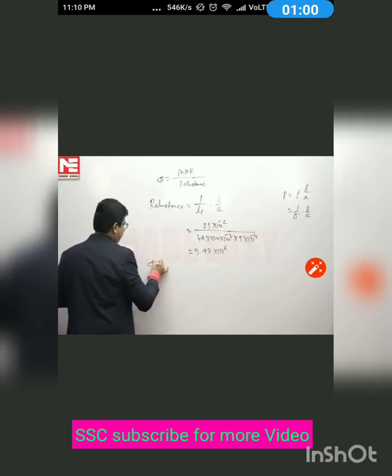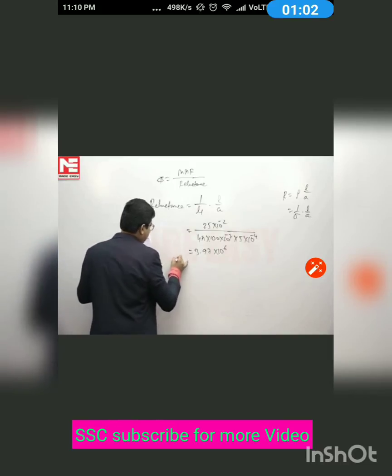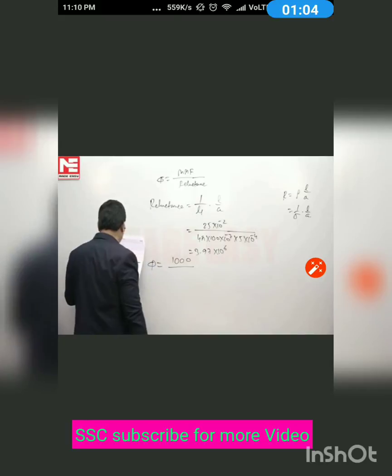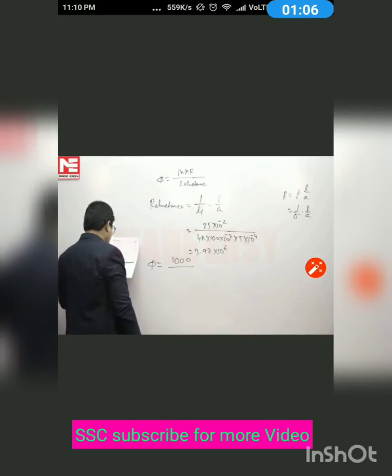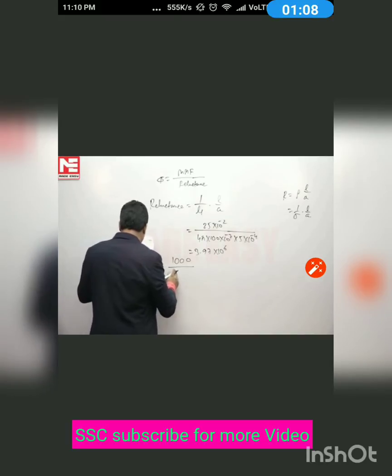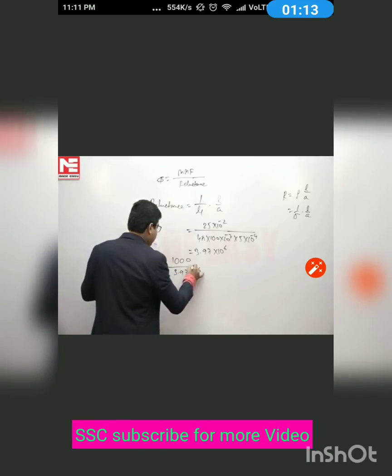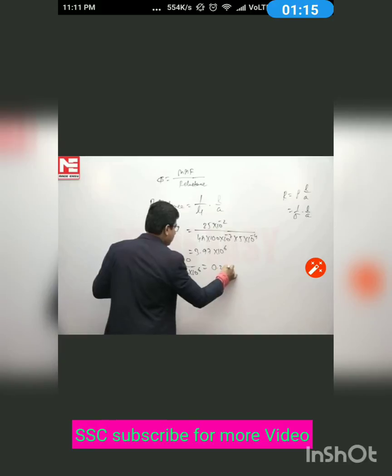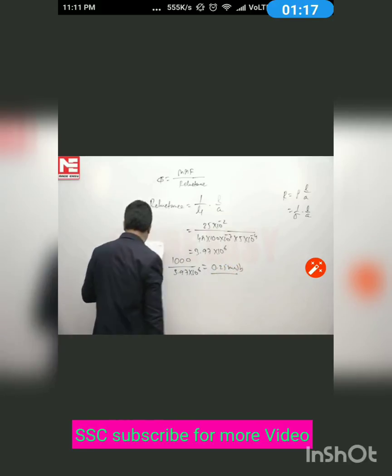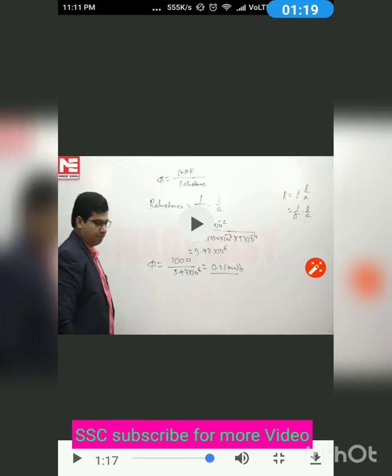So what is the value of flux? Flux is mmf, that is 1000, which is given in the question, divided by reluctance, that is 3.97 into 10 to the power 6. So the value is 0.25 milliweber. So our answer is B.